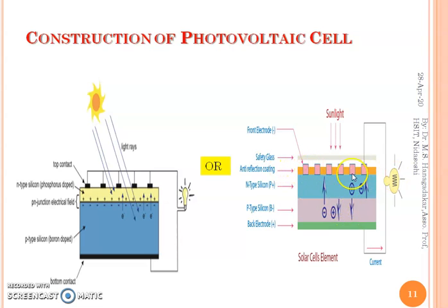And in between the metal grid electrodes, there is an anti-reflecting coating which is made using a compound. You can take silicon nitride, or you can take titanium dioxide, either one. This is the brief information about this PV cell unit. If these dimensions are used for making the photovoltaic cell, there is a generation of electric power of around 0.5 to 0.6 volts. That's the brief information I explained by looking at the diagrams of the photovoltaic cells.